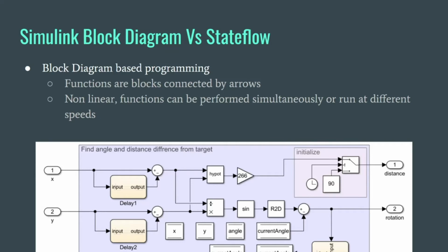So you can have code that is running and then have separate code that is running at a different rate. This would be like moving forward and turning at a certain time versus checking where you are on a line with a light sensor. So you can use this really well for continuous calculation, like cruise control in a car, where it's continuously taking sensor logic, feeding it back into the robot, and controlling it. What it's not good at is doing things at a specific time.